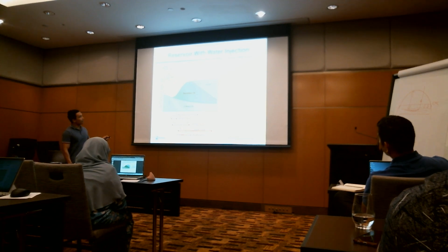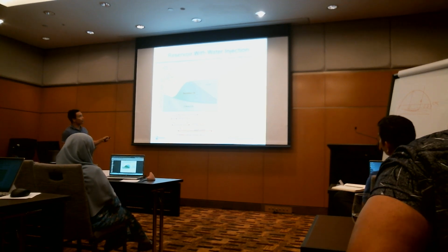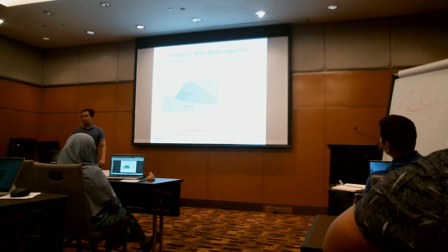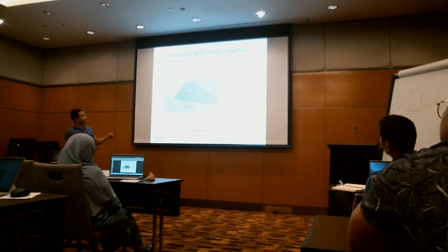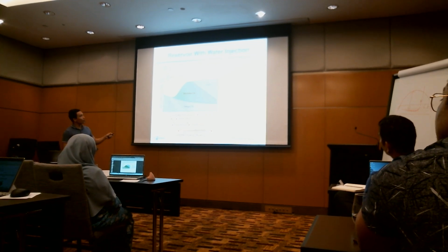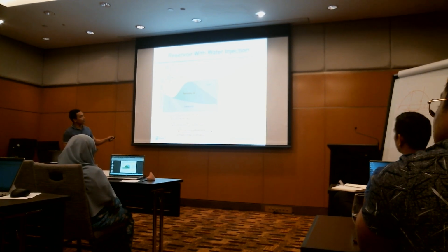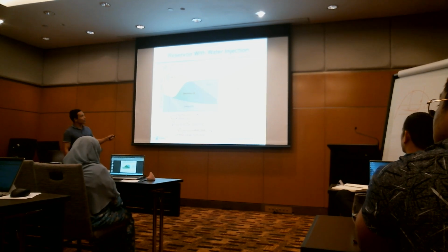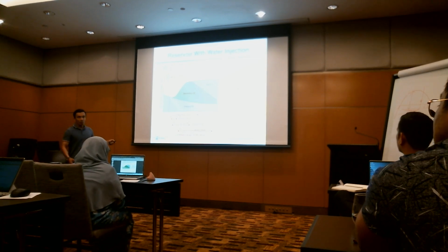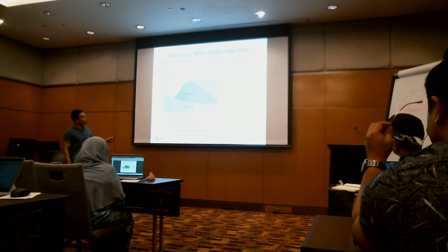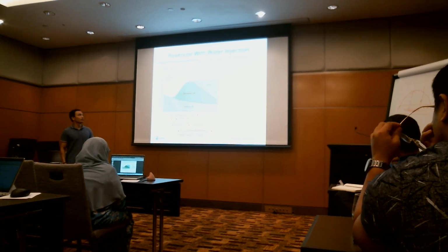After that, the production starts to decline as we start to have the water breakthrough. So the total fluid will be like this, but you can see the ratio between the oil and water. As you produce, your water cut starts to increase more, and you expect your oil rate to be lower compared to the water.